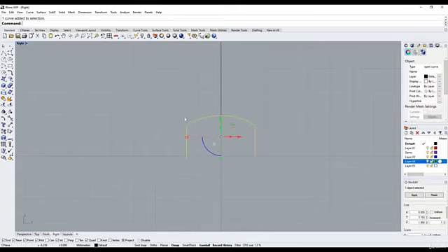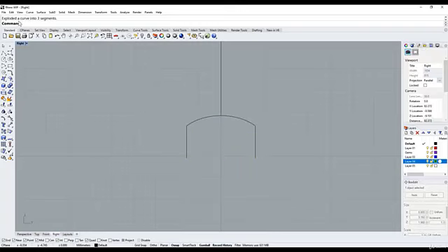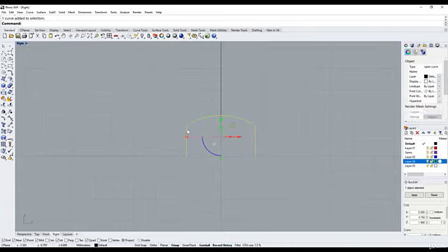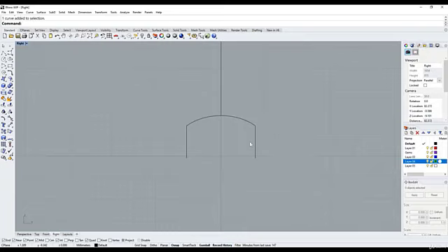Another way of exploding something is this little explosion button here. And you can see up the top there, we've exploded a curve into 3 segments. But I don't want that, I'll Control Z. So we've got these 3 curves as one section.